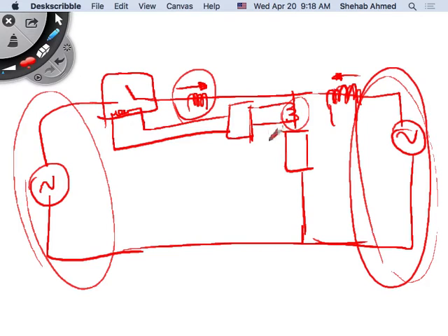And then, of course, I cannot only put a breaker here, because if I put the breaker here, and let's say there's a fault right here. No, the fault happens here. It doesn't happen in this line. It happens right before this line somehow. Right? Two wires touch each other here before your actual load. There's no problem with the load. There's a problem with the cable connected from the grid to the load. So the fault happens here.